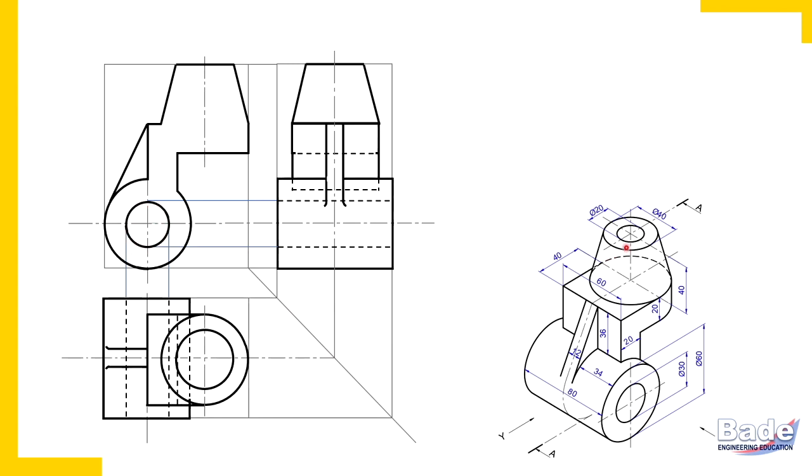Okay, now there is one more hole here. This hole, its opening appears in the top view. So focus in the top view. So this is that 10 mm radius hole. Now project it. It is in that conical portion. But when the depth of a hole is not given, we should assume a through hole. So draw a dotted line showing the opening at the lower side also. So watch here. The hole is from the top and here it is open. So top to bottom, that hole, bottom of that U-shaped plate.